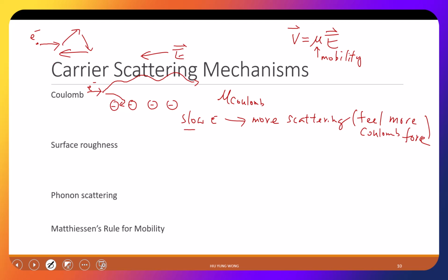So, if the temperature reduces, what happens to the speed of the electron? Is it slower or faster? Slower, yeah? Because, although we did not talk about that, the thermal energy kT over q is equal to half mv squared, because the so-called thermal energy is just the kinetic energy of the particle, right? Of course this is not exact, maybe 3kT over q, or over 2q, whatever. Higher temperature, electrons move faster, right? Electron is just a gas, except it is charged and except that it is in the solid. It's just a gas, right?